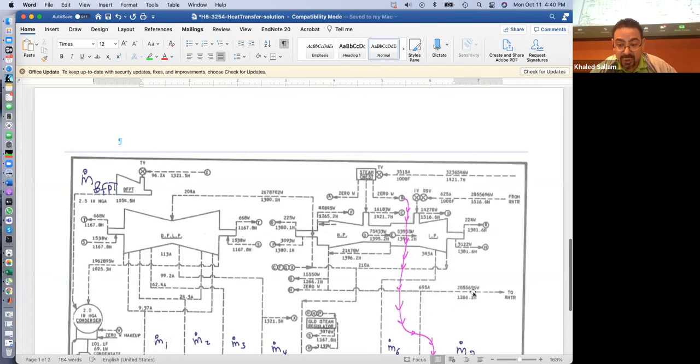Right? Isn't that the pressure going to the reheat? And coming back from the reheat, 625. Right? So again, bunch of pipes, bunch of valves. I mean, don't expect it to go frictionless without anything. It will drop a little bit. But we always plot it basically at constant pressure.